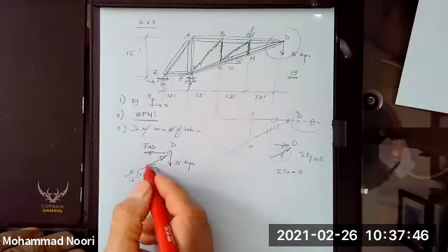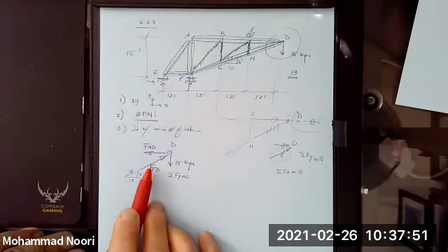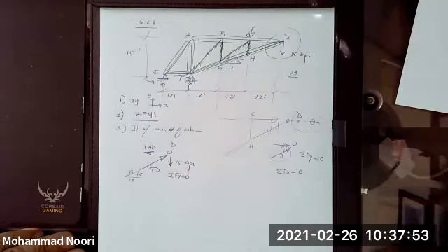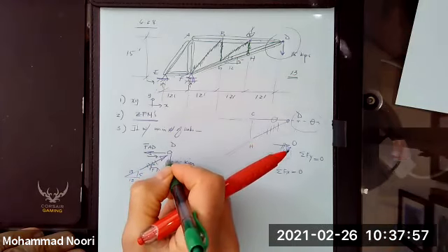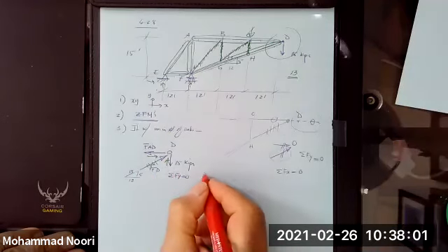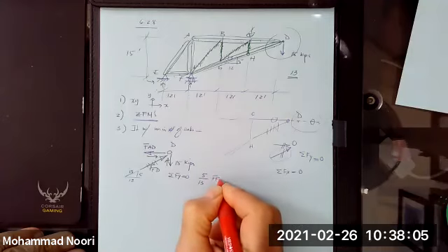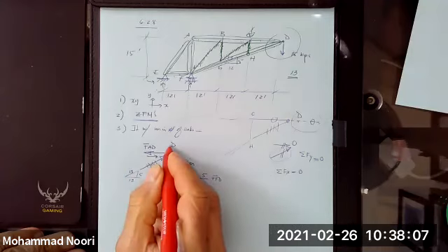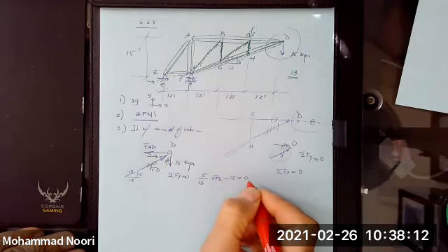So let's try the equations of equilibrium. I will start with summation of forces along y equal to 0 because that would involve only one unknown. Resolve this into its components. This component would be 5 over 13 FD, positive, negative 15 equals 0.